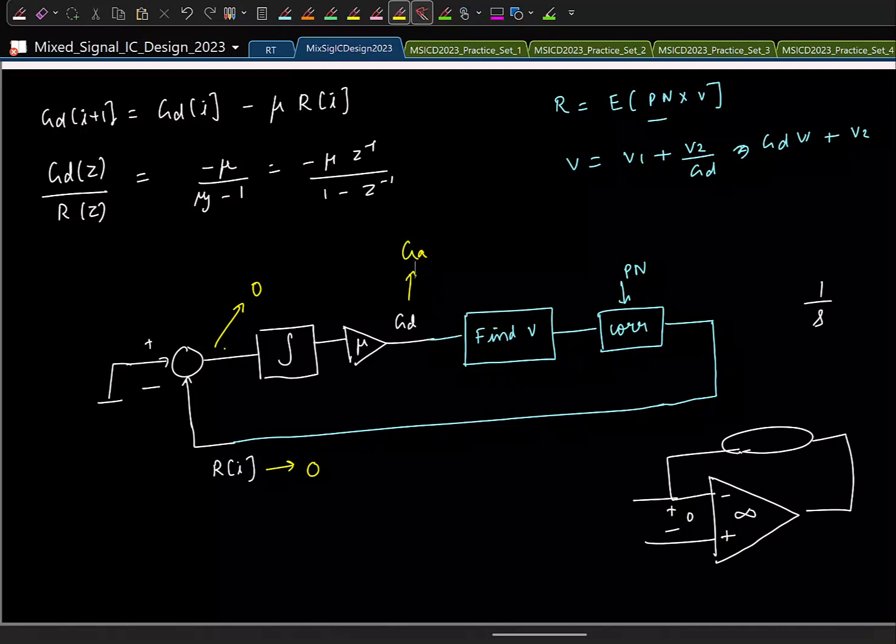So loosely speaking, all these optimization problems, all this optimization we are doing here, LMS or whatever, is basically building a negative feedback loop, and it's exploiting the fact that if you have an integrator put in a negative feedback loop, the error at the input of the integrator will be 0 in steady state. So this is a common basic principle that we will be using in many calibration mechanisms and in many circuits also.